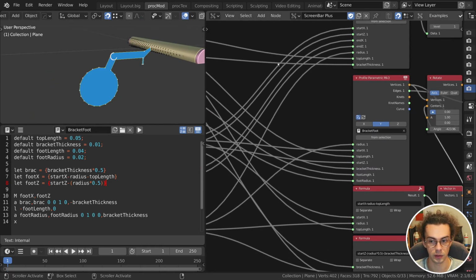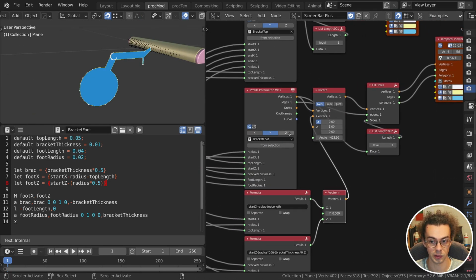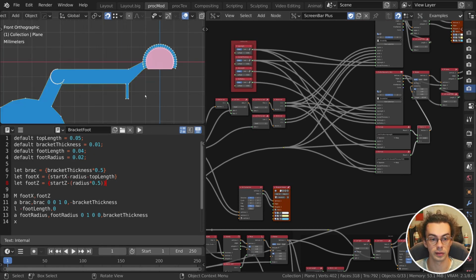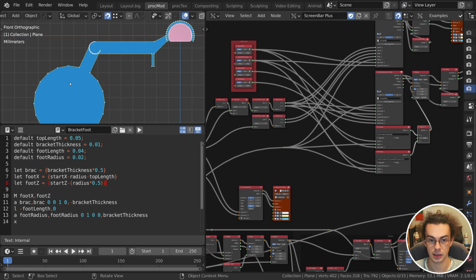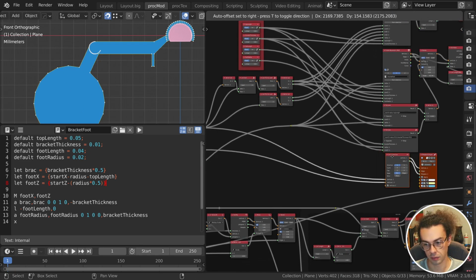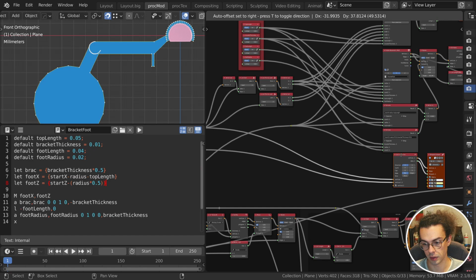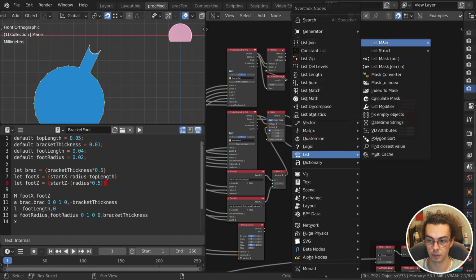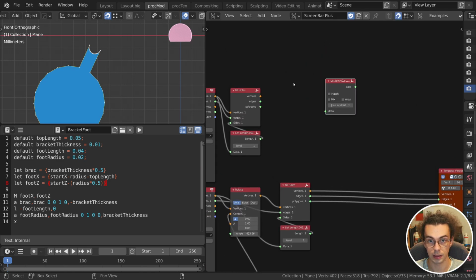So we've used the fill holes to generate all of the faces on here, and we have our initial sort of wrap around the top, around the lamp, top section of the clip, and the back section of the clip. So let me just pull this out here just so we've got everything more or less in the same place. We need to just join these three together. So list main list join. This is going to be our vertices.